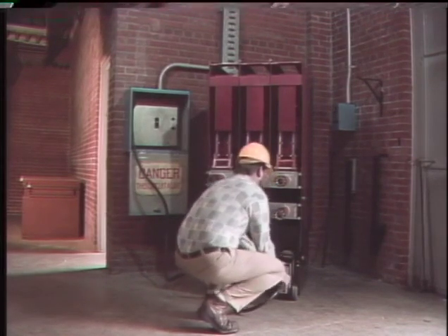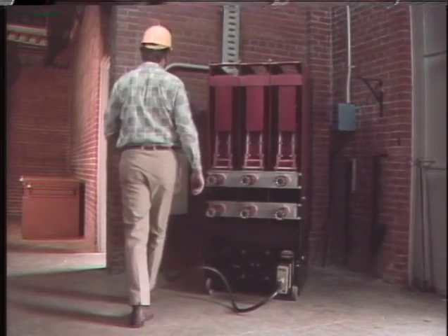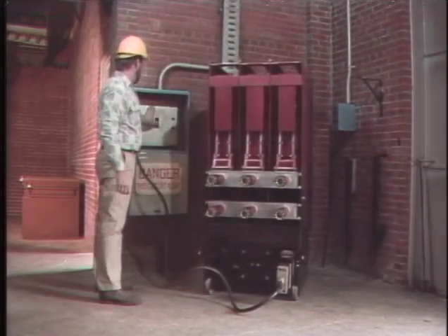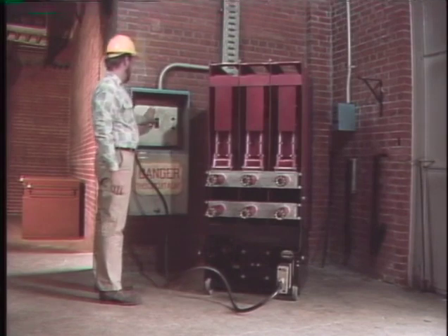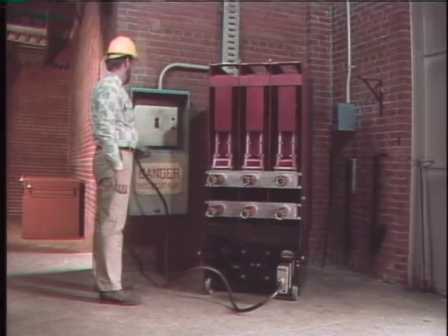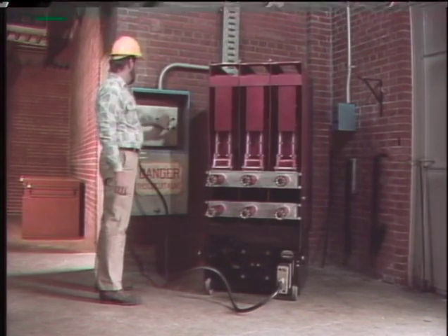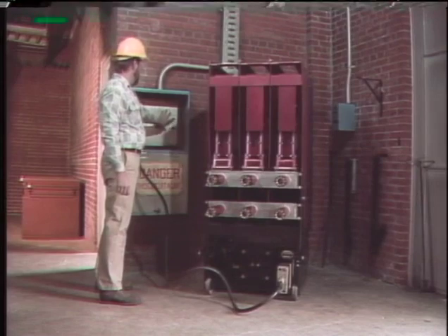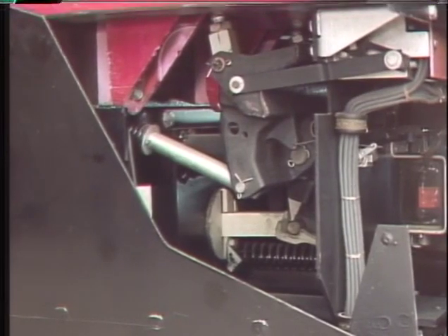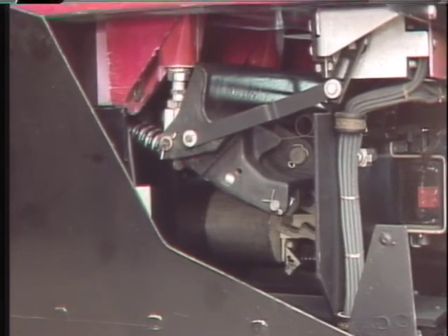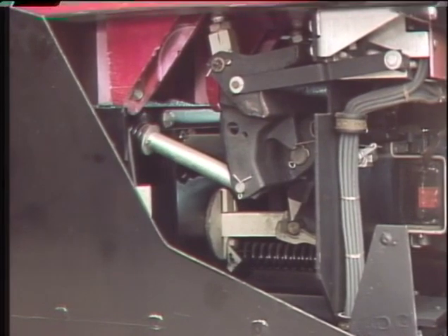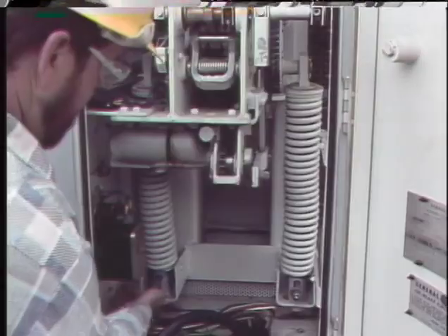To operate the breaker electrically, connect the breaker to a power source and energize the source. Then operate the breaker and listen for sounds that might indicate that the mechanism is not operating freely. If there appears to be some resistance, the power source should be de-energized so that whatever is causing the mechanism to bind can be found and corrected.